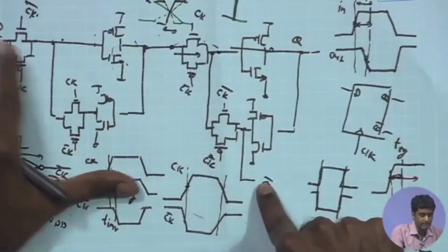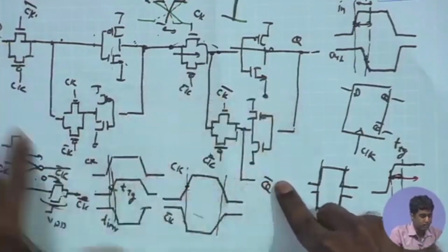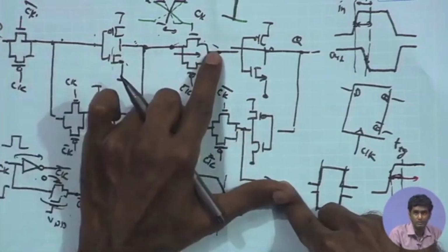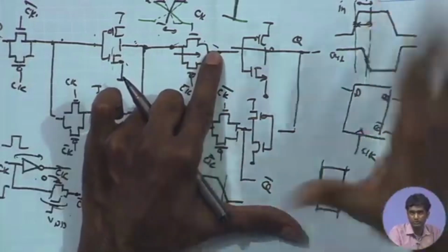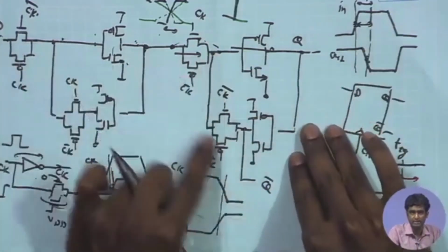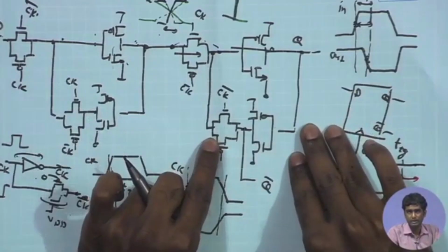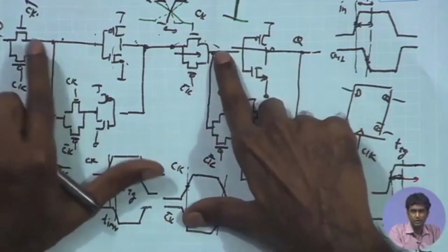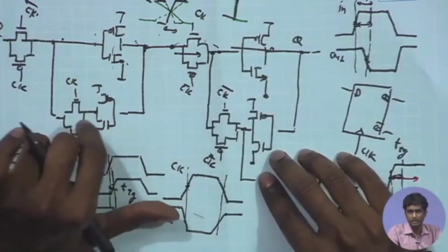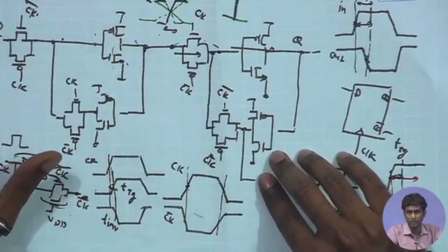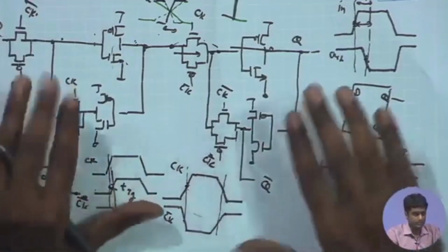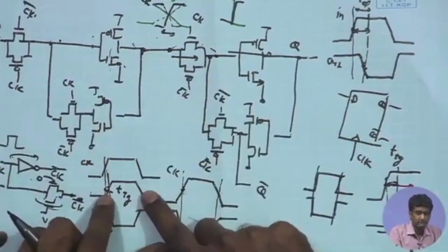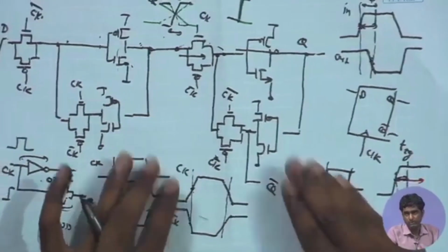So, it is not necessary that the Q bar will be reliably copied back to here, because the polarity from this Q bar to this point may not fall to 180 degrees at that same instant, because all these latches are getting on together, and as a result I can have the wrong transition over here, and it can lead to erroneous phase in the counter output. So, the hold time will become important, and the rise time, fall time, and the overlap in the clock and clock bar will become important in our application.